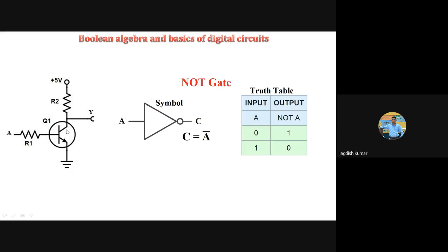In that case, there will be a very low current, or theoretically, negligible current. And if no current flows through this resistance, what will happen? There will be no potential drop across this resistance. And if there is no potential drop across this resistance, what will be the potential here? It will be exactly equal to this value. If current is 0, no potential drop across this resistance, so potential here and potential here will be exactly the same. And hence that will be nothing but 5 volt.